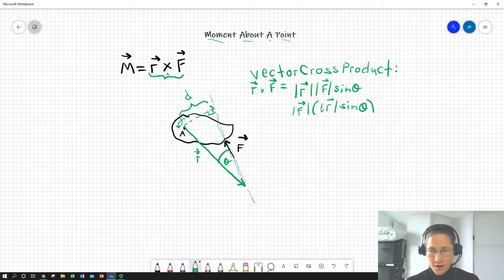So the cross product basically gives us an expression for the magnitude of the force, we'll just write it without the bars, meaning magnitude, times d over here, which is defined as this. And if anyone looks back in physics, you might see an expression for torque equaling force times distance, where it was implied that that distance was always perpendicular. Well, that perpendicular distance was brought to you thanks to the vector cross product.